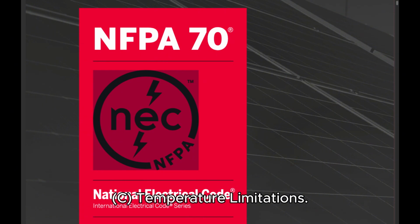C. Temperature limitations. The temperature rating associated with the ampacity of a conductor shall be selected and coordinated so as not to exceed the lowest temperature rating of any connected termination, conductor, or device. Conductors with temperature ratings higher than specified for terminations shall be permitted to be used for ampacity adjustment, correction, or both, as appropriately modified by 310.15(B)(7).